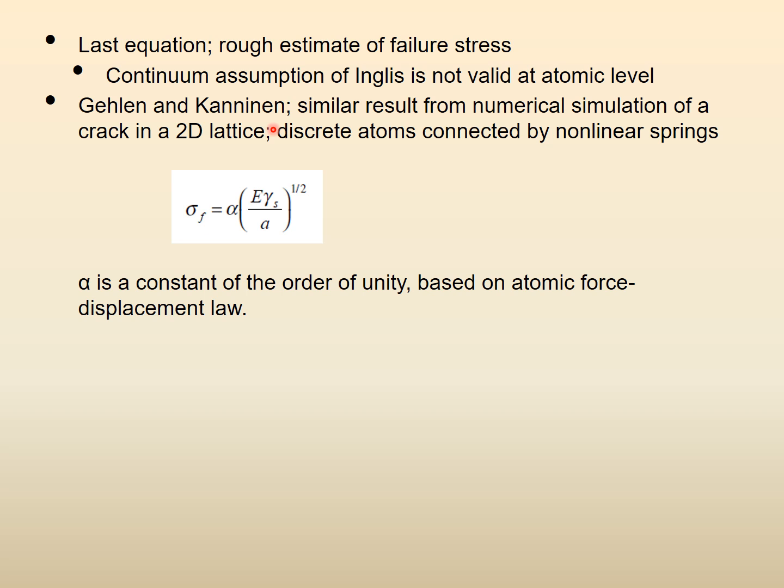So it is not a continuum, it consists of discrete atoms connected together, and in the numerical simulation each connection is like a non-linear spring. We don't go into the details, but if you have done an applied finite element course, that is the basis. The connections between material particles are spring loaded connections, and here they are non-linear.